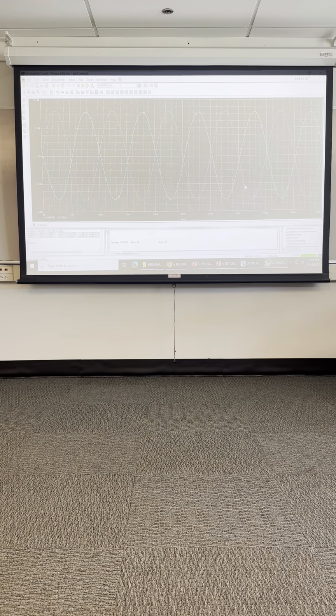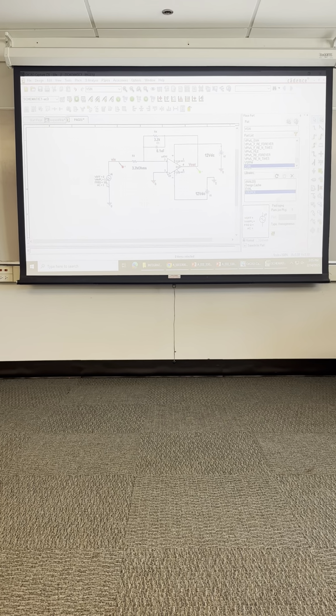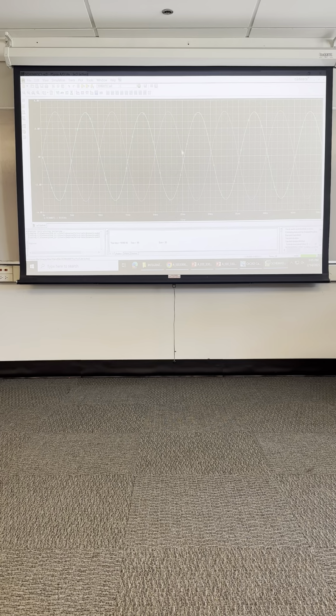Okay, so it was just instantly filtering it out, effectively, the gain was almost 0. The filter now has only 100 hertz input. On the plot, V out and V in are the same, except inverted. Is this correct? Yes, it is, because it's an inverting op amp with a gain of -1, and it shouldn't be getting filtered at all at frequencies inside the passband.